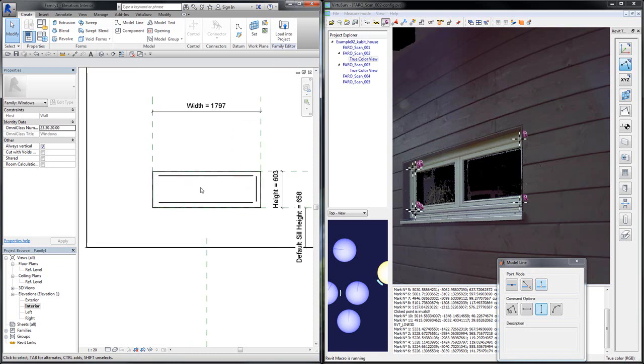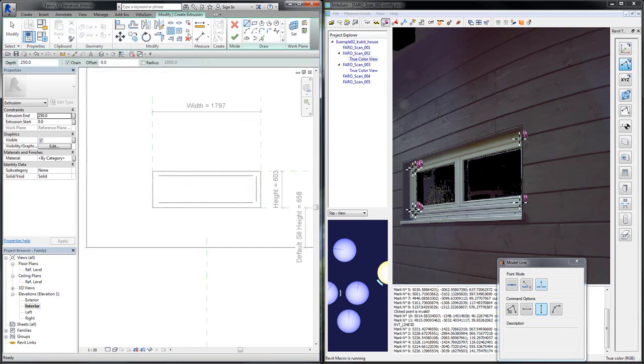Okay, switch back to Revit and start an extrusion. So Revit turns over to the sketch editing mode, and again I can choose the pick line tool. First I will select my opening cut, and with the tab key you can toggle through all elements under the mouse cursor and select the opening cut here, and I will also close all these locks so that my window frame will be connected to the opening.